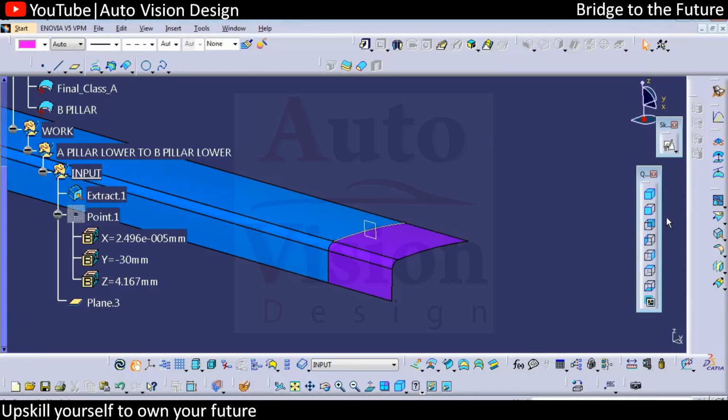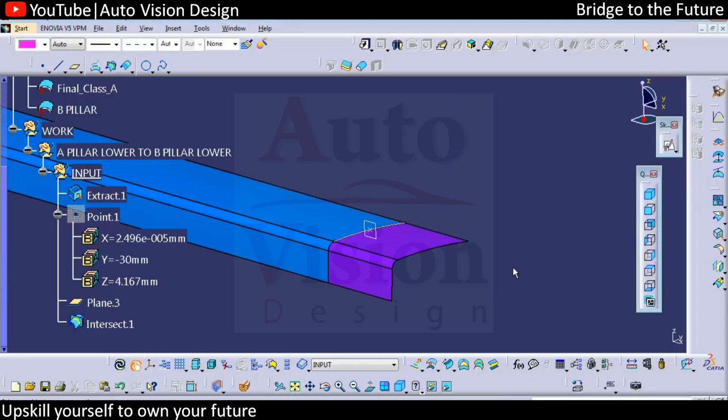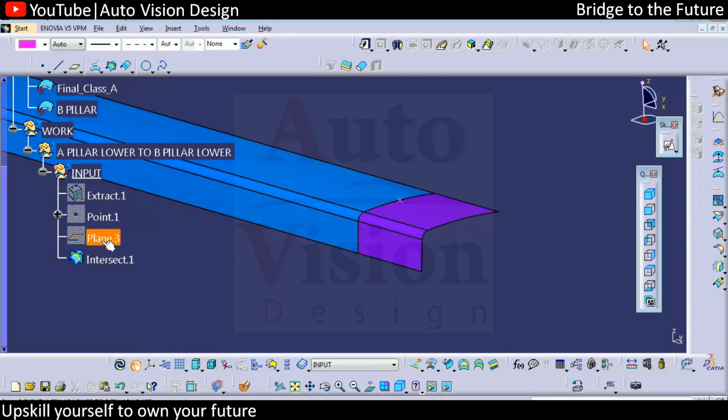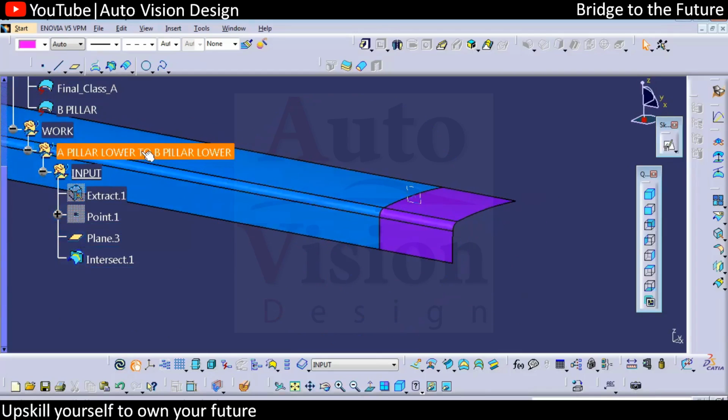Now we take the intersection of the point on this curve and this plane. First of all we have created a point at y30, and with respect to that we have created a plane on that point, parallel to x and z. With this curve we have taken the intersection, so this will be our input point. Okay, so what we have created is nothing but the construction work we required. To this point we now have this plane, and to that plane we need to create a master section.